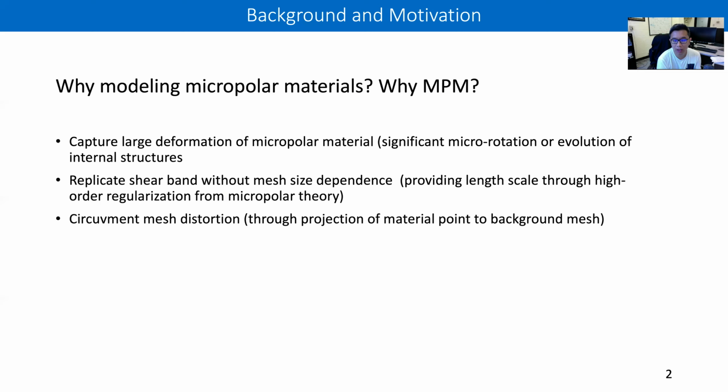And the material point and the micropolar method are a good match to each other because the material point method can help us overcome the significant change of topology due to the onset of shear bands, and in some cases even model a free surface problem for fluid mechanics without concerning about mesh distortions or the need for remeshing purely due to mesh quality deteriorating from large deformations.